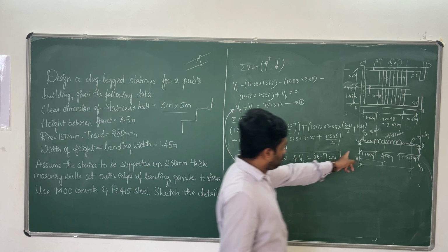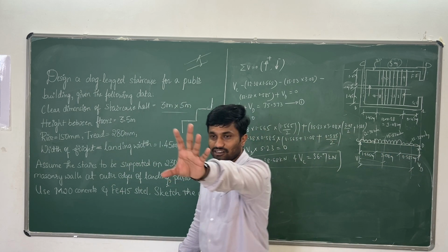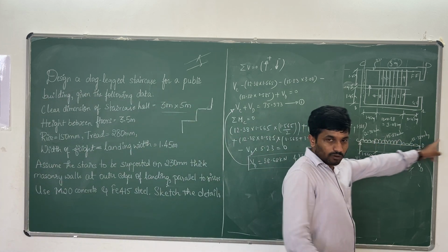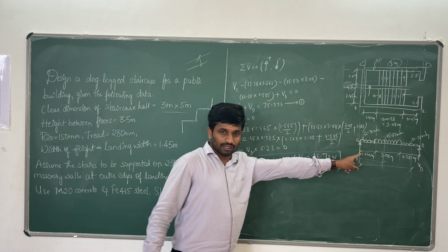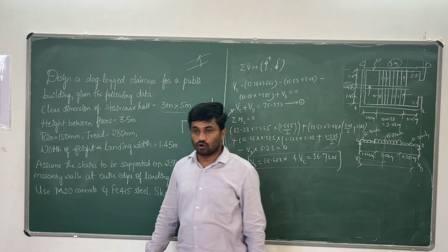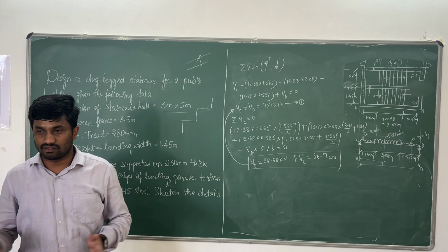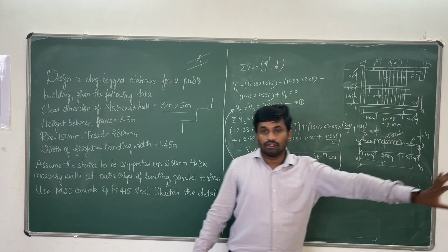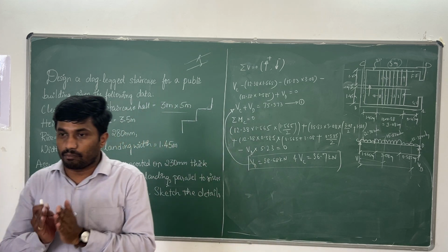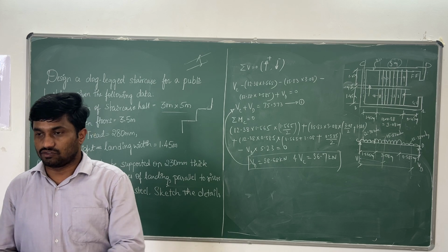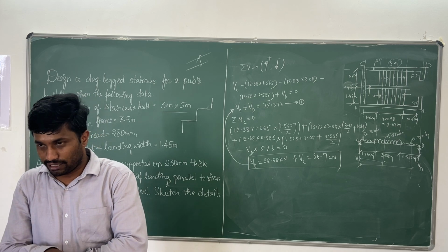Generally, you know that if it is symmetric load, then you may expect a mid-span maximum bending moment, but it is not a symmetrical load. Here we are having one weight of UDL, but here it is maximum. So it is uneven. Therefore, when it is uneven, at that time you have to compute a point where the shear value will become 0 to get maximum bending moment.